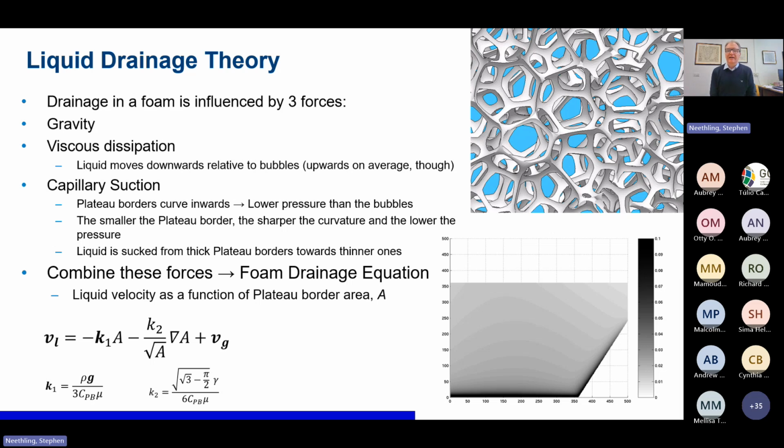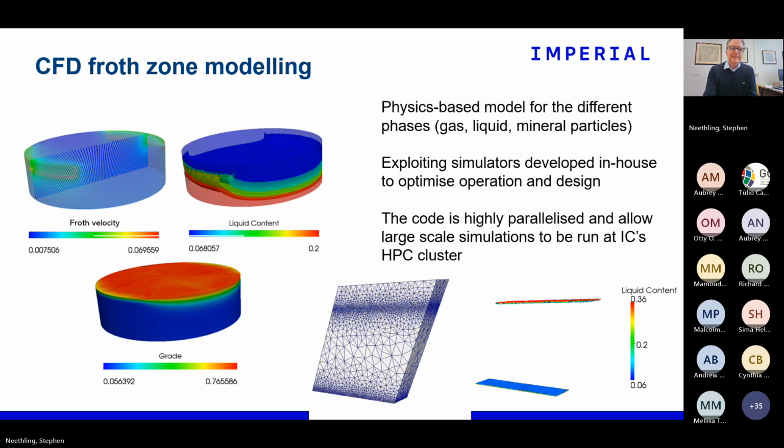And so once you combine all of these three forces, you get what's known as the foam drainage equation. And this equation is really fundamental to our predictions of the foam behavior. And we use this to produce CFD-like models of the froth phase of flotation.